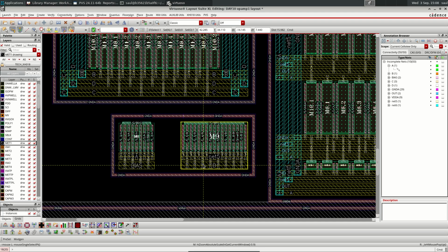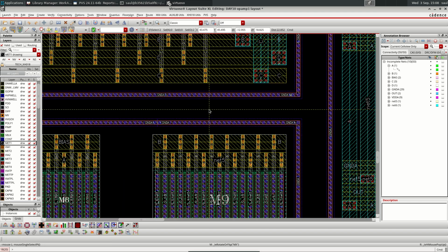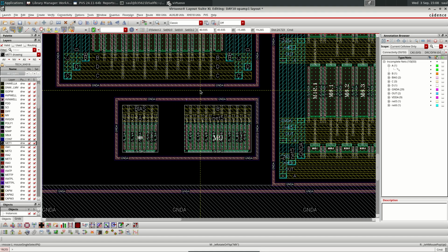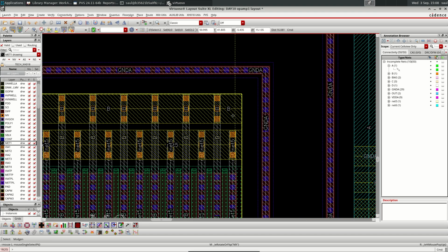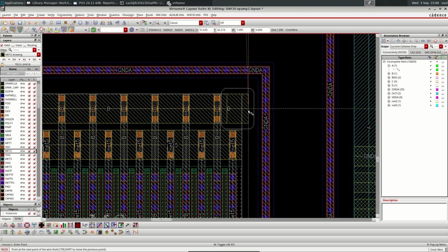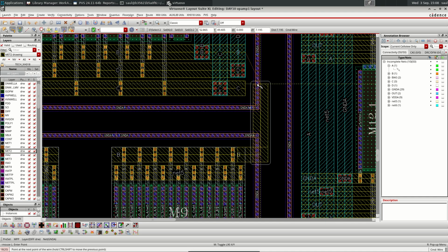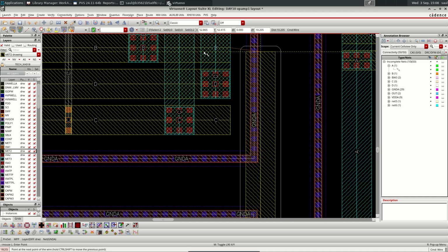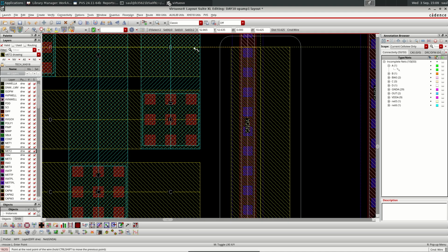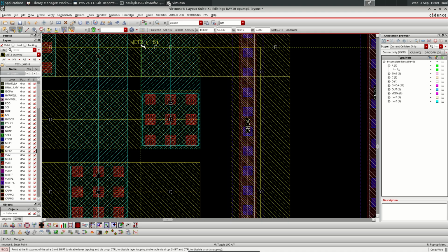And we see that it is probably much more useful to have these transistors flipped vertically, so they get a little bit closer and reduce the parasitics a little bit. So we have node B and node B here. Okay, now I'm going to bring this. We can connect it like this, B. You notice that the tool is telling me the minimum spacings that I should respect. And then connected, and we can see that node B has disappeared.